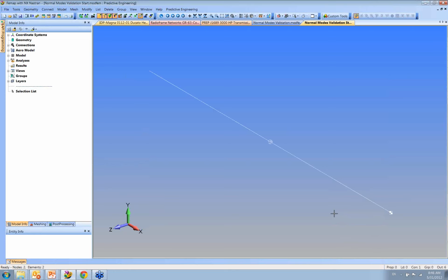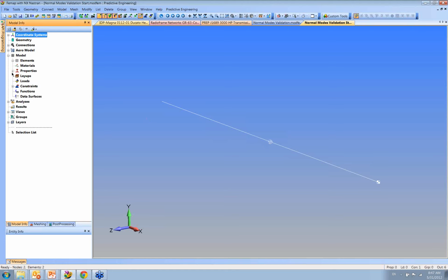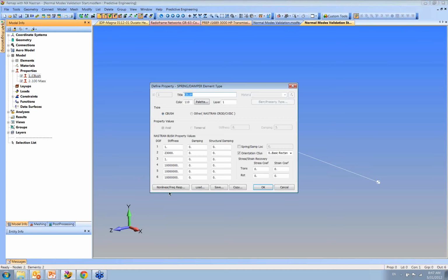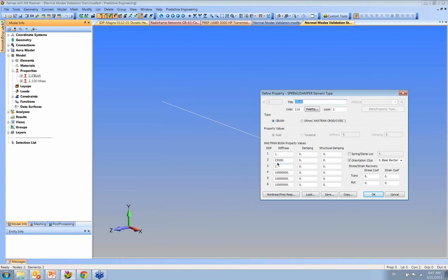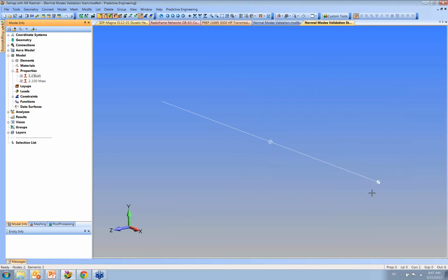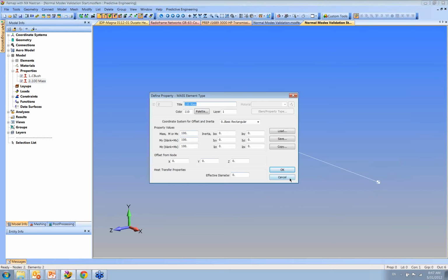Okay. Voila. It's there. In this model, I'm using a C-bush element. Now, I'm going to have these notes, and most of the models I'm showing here, all in a package that you can download from the website. So if you want to see where this is going and practice on your own, you can. So this is a C-bush element. I've given it the stiffness in the vertical direction, which is the Y, 2300. No stiffness, more or less, in the opposite directions, and then super high stiffness in the rotation. So it has six degrees of freedom. And then it's just a mass element tied out to the end.